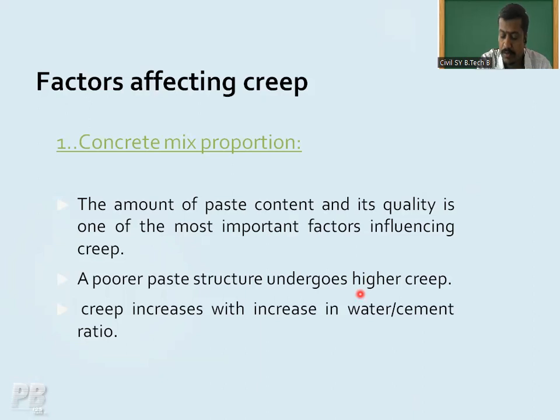If you are going to cross those limits of minimum and maximum water cement ratio, or minimum cement content, then definitely it will affect the strength and durability of your concrete. So mix proportion, again, plays a vital role. Okay, just a minute, please.